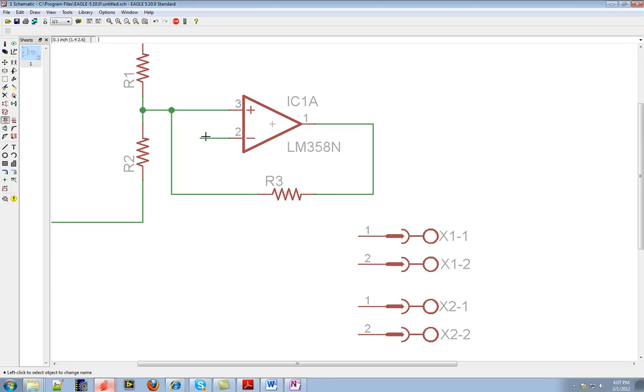Okay, I can't see that yet until I do the label tool. So I want to label this net now, so I just left click on that. When I click on this net now, it's showing me the label, VN. If I wanted to see the label for this node, what was it, N3 or N4? Okay, so I don't necessarily want to label those ones, just the ones that I force a name.